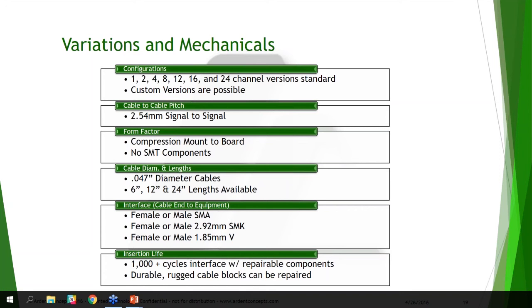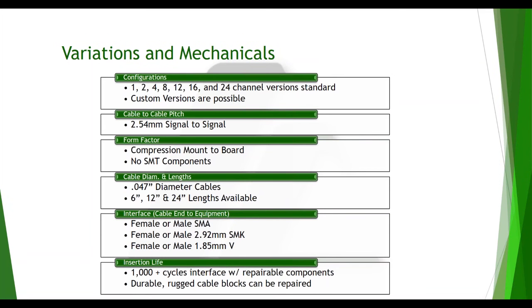So if you have a special cable length, we've talked to you about that. Happy to. We do phase matching. Our standard is plus or minus 2 picoseconds, but we also do plus or minus 1 as a special order where it becomes more or less a sorting operation. But plus or minus 2 is our standard. And that's plus or minus 2 across the whole connector, all the connectors, not just any 2 pair.